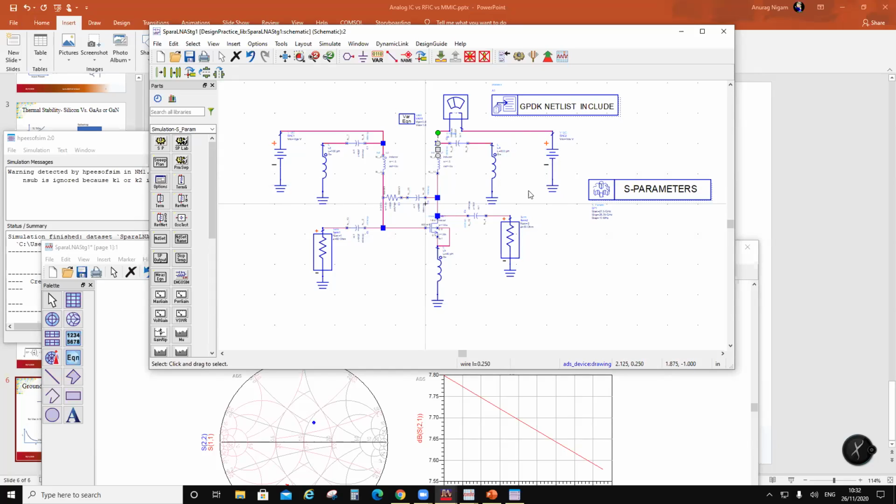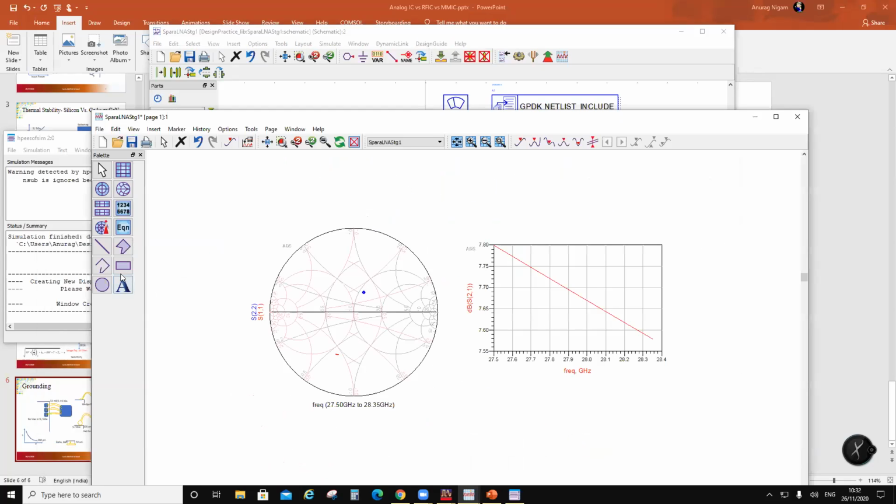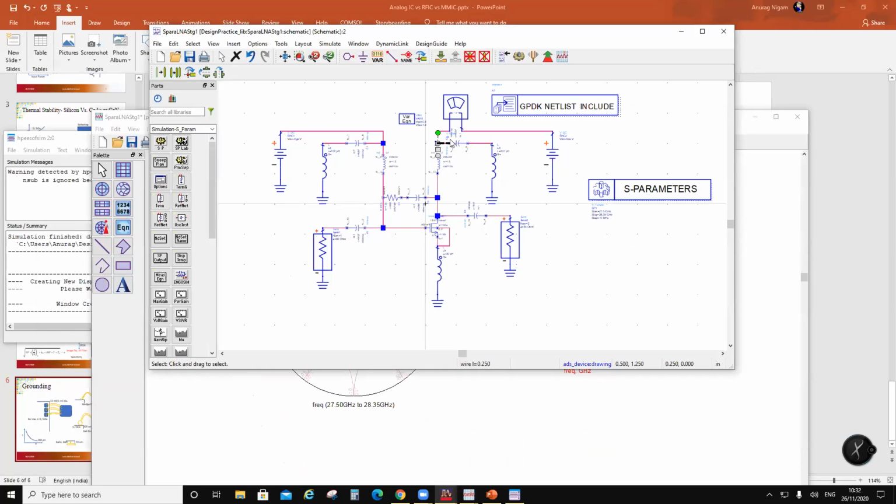But when you do a modulation, and there are all forms of conversions, then this is going to make your ACPR numbers worse. So you have to have a very good ground over here. Okay, so you have to use sufficient capacitance for bypass here. If you are in RF and you are not able to get sufficient capacitance, what's going to happen is the following. The capacitors have something called ESR. That's why you put many capacitors in parallel, because their ESRs are going to come in parallel and they're going to give a very good ground here.